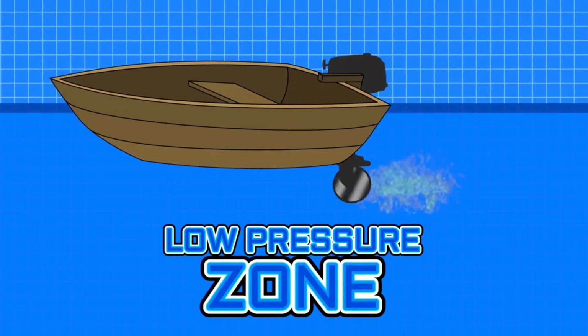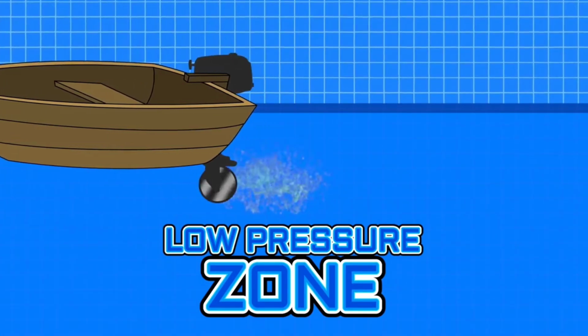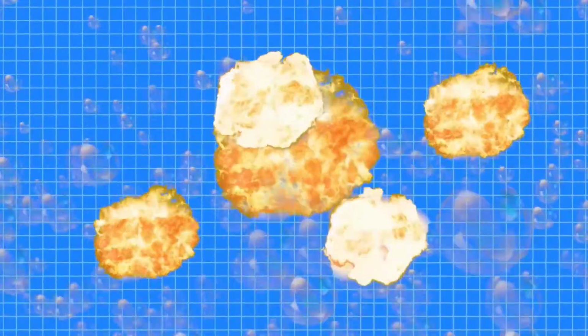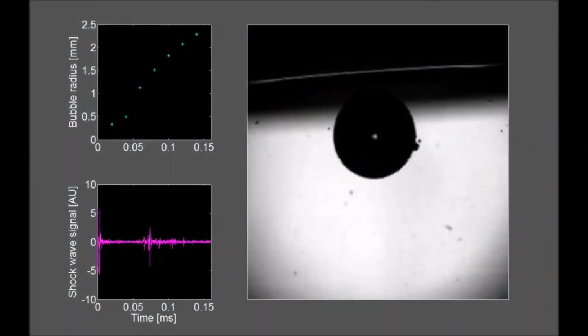With vapor bubbles in the low pressure zones of the pump, the motor's energy is wasted expanding the bubbles instead of bringing more liquid into the pump. As the bubbles pass into the pump's high pressure zone, the motor's energy is wasted compressing the bubbles instead of expelling the liquid from the pump. Bubbles can collapse as they pass from low to high pressure zones in the pump.